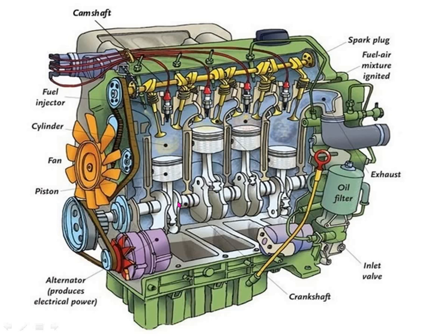This crankshaft rests in the crankcase by the crank bearing, and connecting rod is also attached with the crankshaft bearing. The piston slides in the engine cylinder in reciprocating motion, means upward and downward motion.